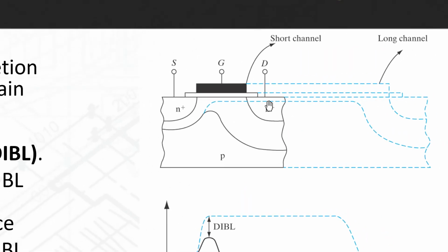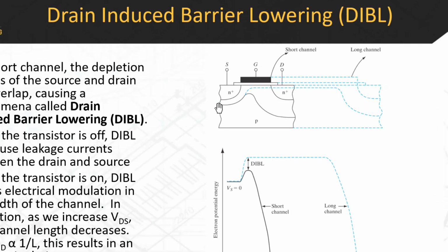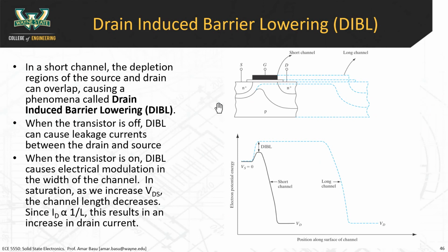If we look at just underneath the gate, the gate has a depletion region throughout the channel already. That depletion region already creates some negative charge, and to compensate for that negative charge, you have to add additional charge into the gate. So it changes your threshold voltage. Actually, that's the first effect.